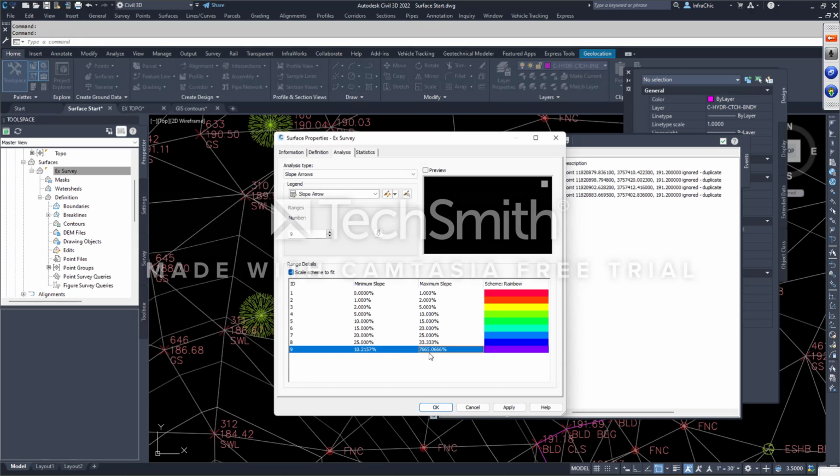Now, there is no way in God's green earth that we have a spot. It probably is, but 76, 65 point, whatever. 100, 33.333. Okay, so that tells me when I turn on my slope arrows, any purple arrow is exceeding a design limit. I cannot use that, or I need to fill it, or I need to change it if I'm going to be touching that piece of ground. Okay, if I'm not touching that piece of ground, it can stay purple for all I care.